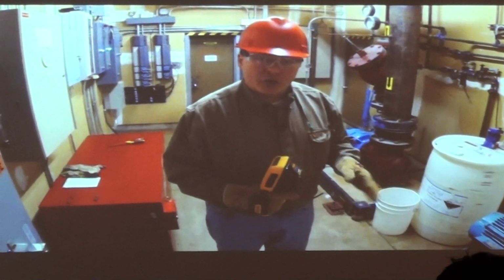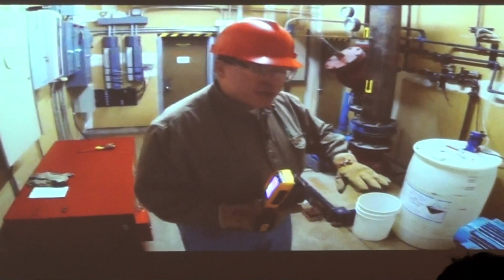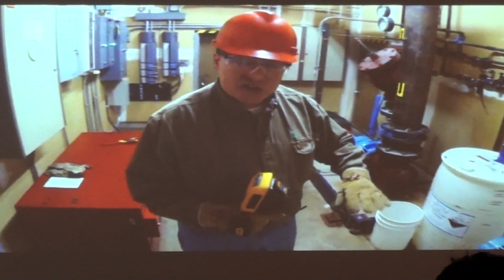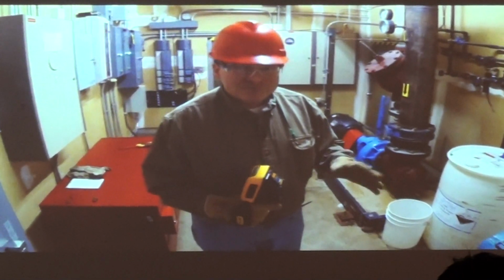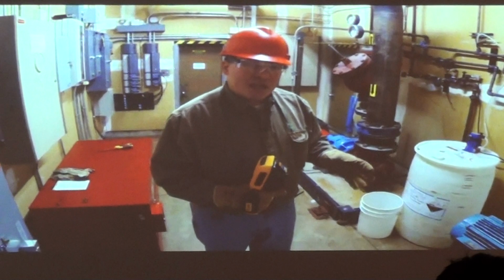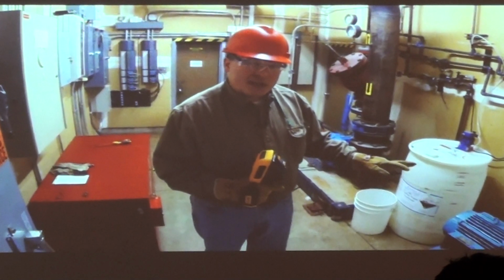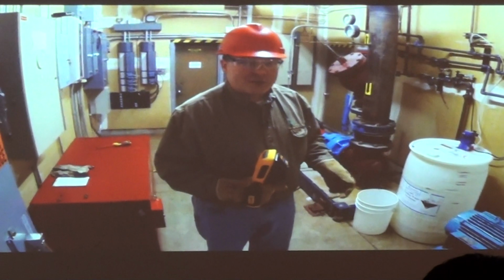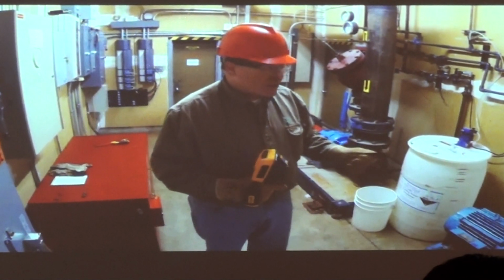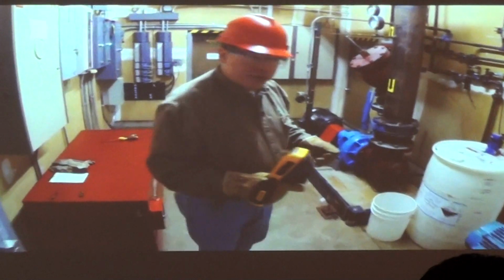In a normally operating motor, you would expect nice, even heating and distribution across the entire housing of the motor. If you see anything that's off, that could be indicative of a problem. Likewise, if we look at this motor and it's running a lot hotter altogether over the entire motor housing, that's an issue as well. So let's take a look first and see what we find out.